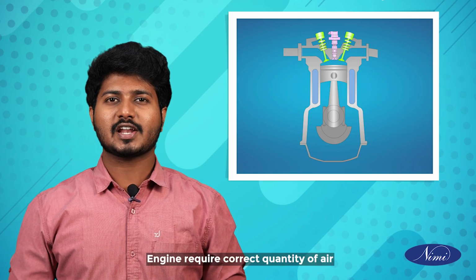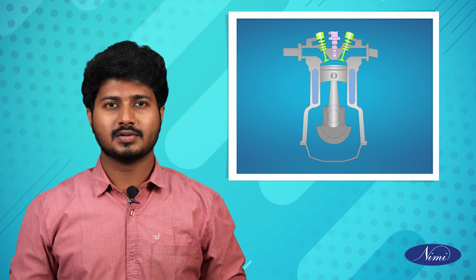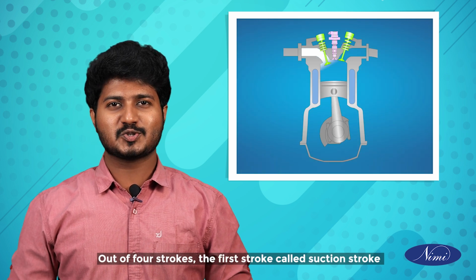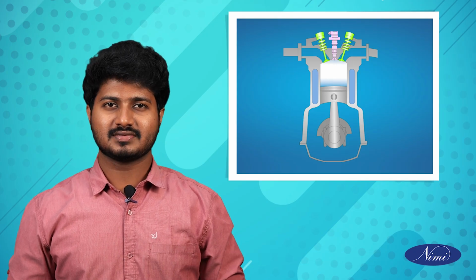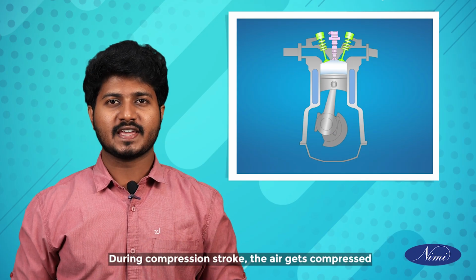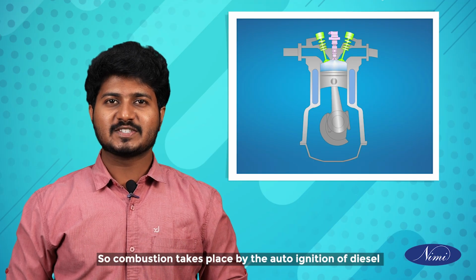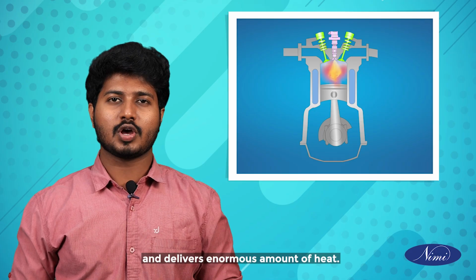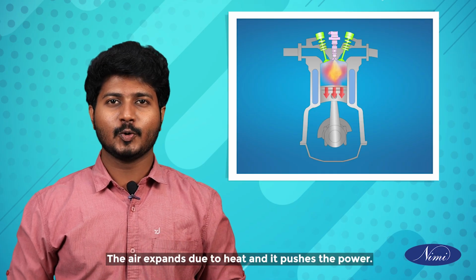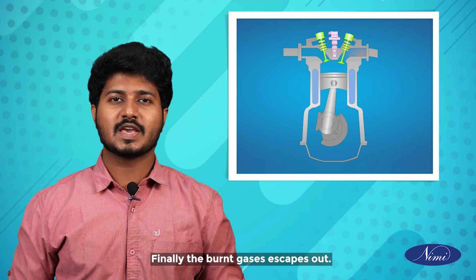The engine requires the correct quantity of air and fuel mixture for combustion to develop power. Out of 4 strokes, the first stroke is called the suction stroke, which sucks in air in the case of a diesel engine. During the compression stroke, the air gets compressed and at the end, fuel is injected. So combustion takes place by the auto ignition of diesel and delivers an enormous amount of heat. The air expands due to heat and it pushes to produce power. Finally, the burned gases escape out.